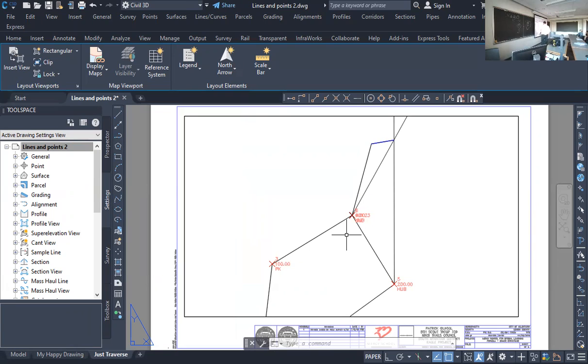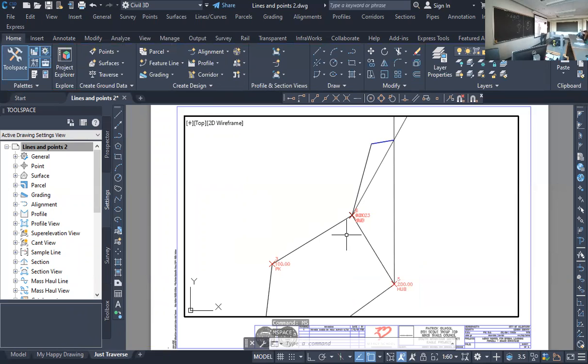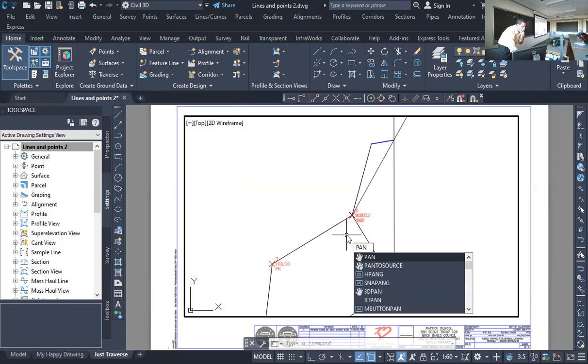Okay. I'm in paper space, right? Yes. I can go down into paper space or down into model space from paper space. If I type MS for model space while I am in paper space, you see how this popped up? Now I'm down here in the viewport. Now if I type the word pan, P-A-N, a little hand.